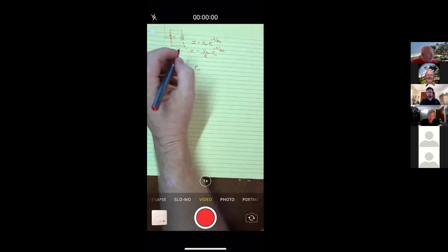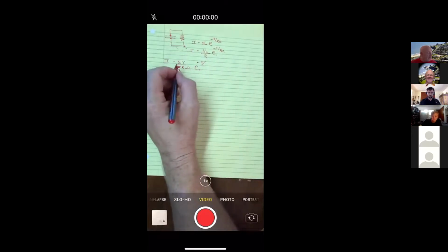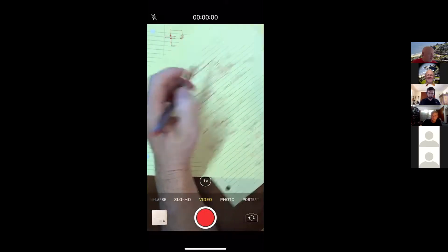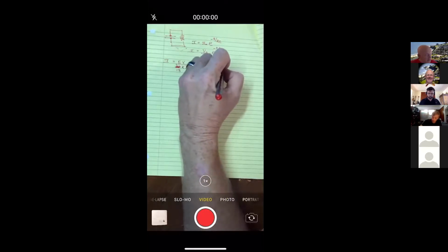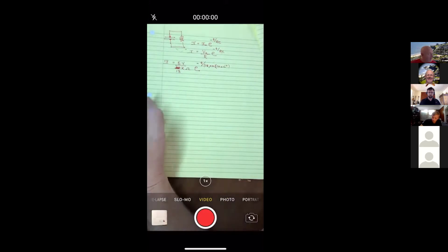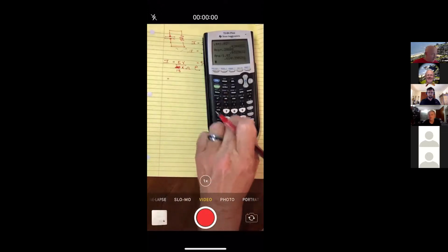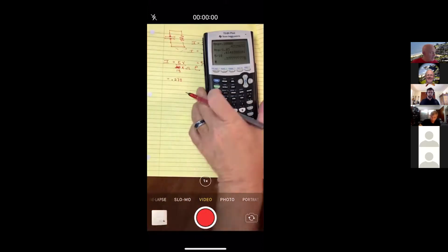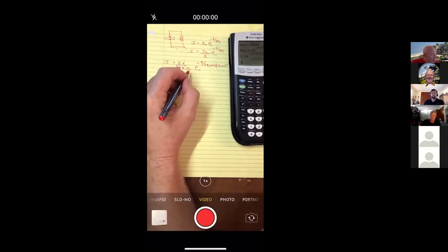And then it decays with time. And this is what we call our RC time constant. And the R, again, is the total resistance, which in our case would have to be the 18,000. And the capacitance is the 10 millionth. All right, so if I grab my calculator and go 5 divided by 18, that's 0.278. And I'm going to play the same little trick: a 1 over kilo is a milli, and a volt over an ohm is an amp.